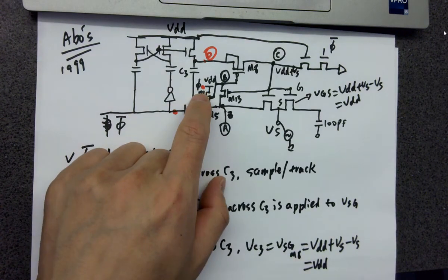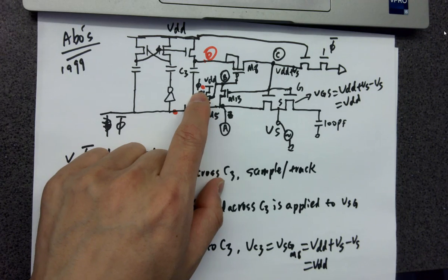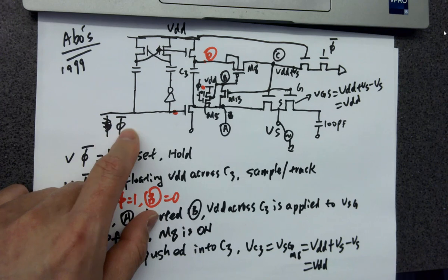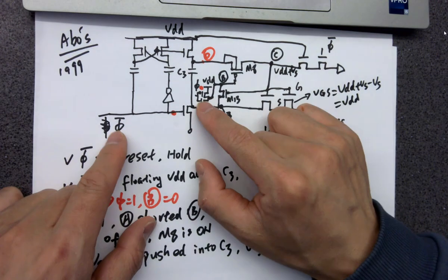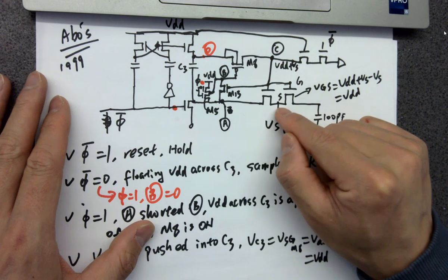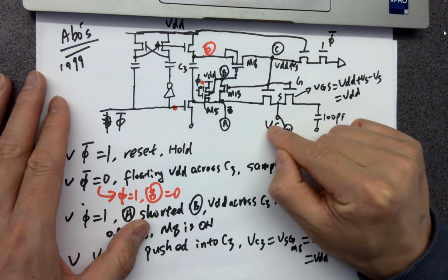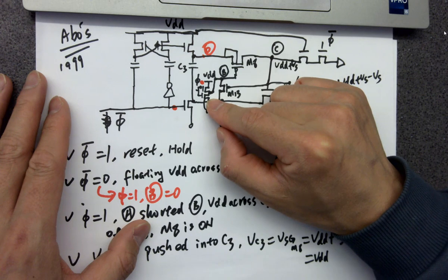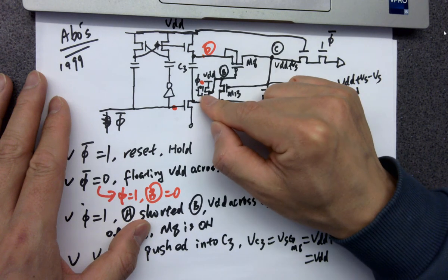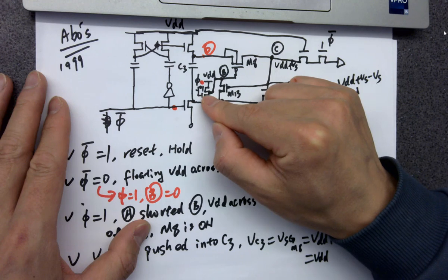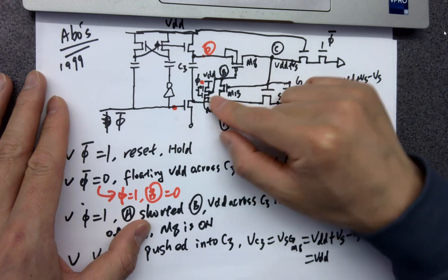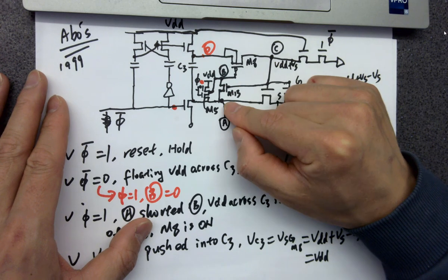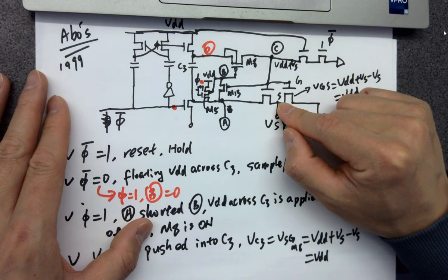So the voltage here to turn on this PMOS is not a high voltage. It's the original 0 to 5 volts logic, the regular VDD to 0. Okay? So just in case the signal over here is larger than VDD minus VTHN, this NMOS will be off, which is bad. So you need an NMOS transistor that has a higher gate voltage in order to pass, no matter what signal is available over here.